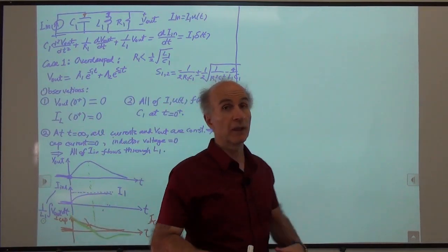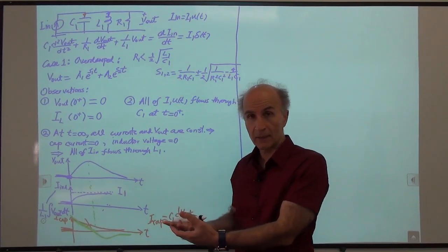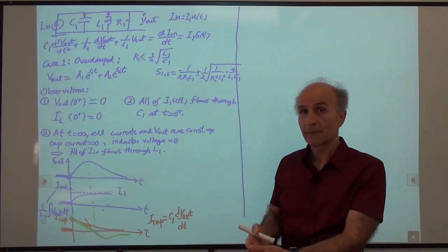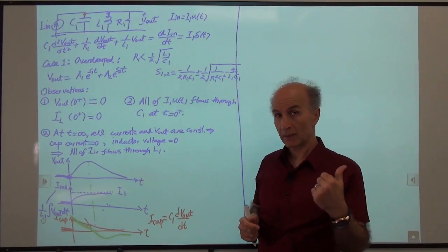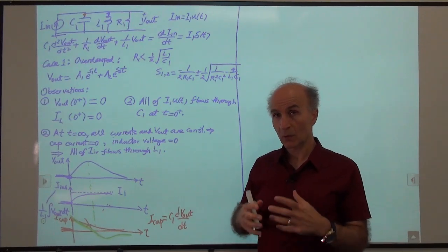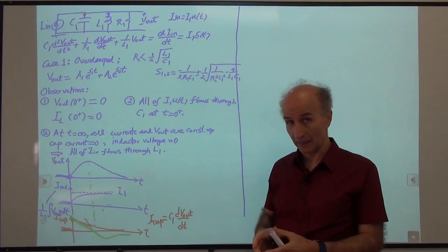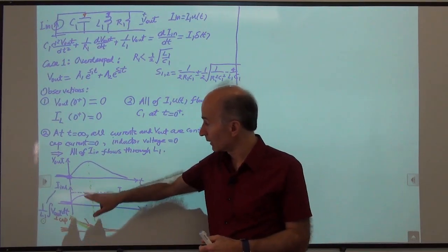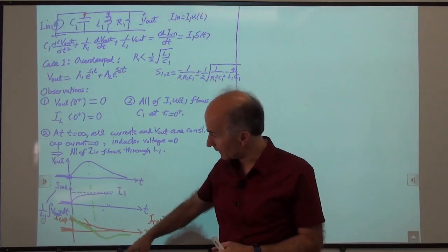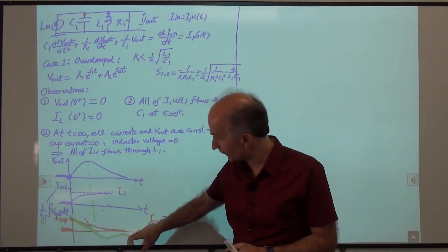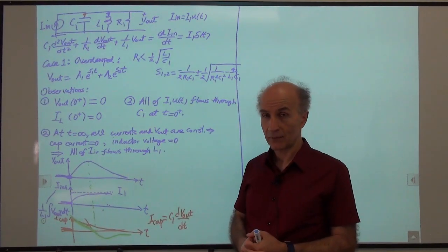All right, so there is some difference between what we see in this driven case as far as V out is concerned and what we saw last time for the natural response. In the case of natural response, when we release the circuit with only a voltage on the capacitor, we saw that V out had a dip, right? V out would start from some value, go down and dip back. Whereas here, it's the current through the cap that has a dip, but V out and the inductor current do not have that response.